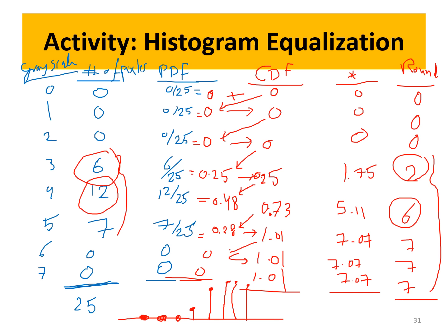Make sense? How we do that? Now, here's the important thing. I want you just to know the probability distribution function, the cumulative distribution function. You multiply with the largest bit that you have, the equalization level that you have, which is 7, and then you do rounding, and you replace each one of them with the values that you should have. So we moved from the blue that was, 1, 2, 3, right, into that. So that's equalization, called histogram equalization.